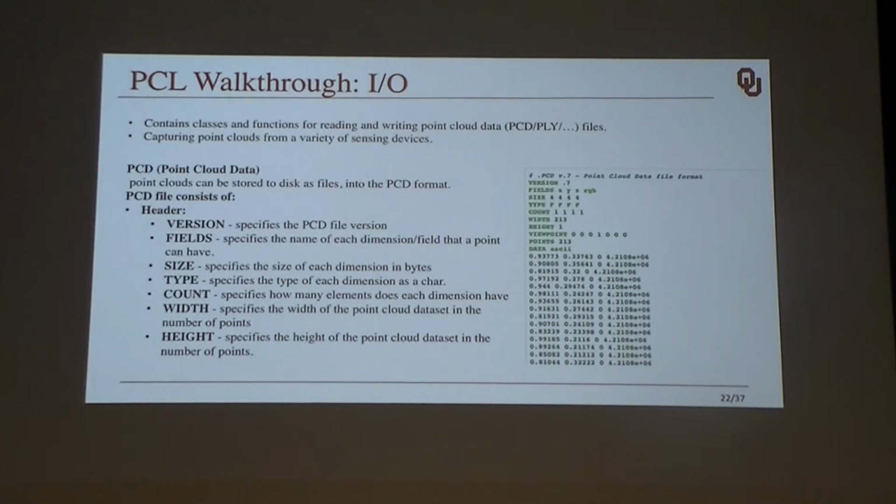It's called an organized point cloud. It has a format which is optimized to work with point clouds. The format is simple. There is a header containing some information like version and fields. Here we have XYZ and RGB, so the point type is XYZRGB. Here is the information about the header, and after that the information about the points. If you want to work with PCL, it's recommended to use PCD. But if you want to use other point cloud extensions, they're supported.